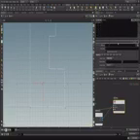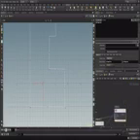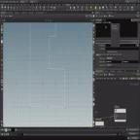So that's going to be this output, so I'm going to call this prim points and also label it prim points. There we go. And that's this variable, and this is going to be equal to the function prim points, $geo, and then $prim num.